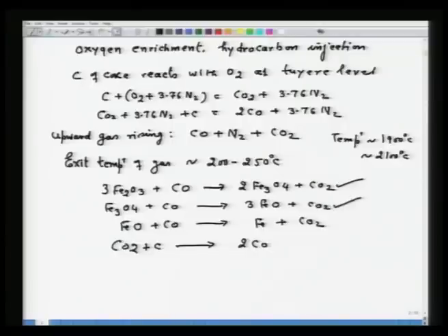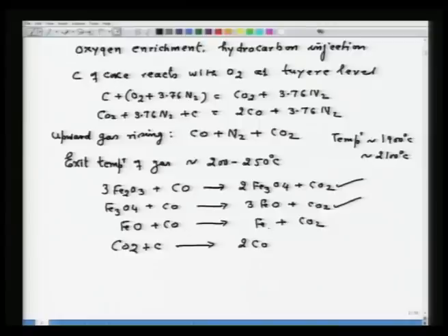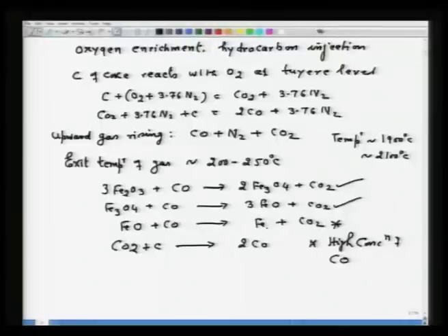Now, one important thing to note, these reactions do not require a very high percentage of carbon monoxide. So, they can occur towards the upper region of the stack, whereas the reaction FeO plus CO is equal to Fe plus CO2 requires high concentration of CO, and at around 900 degrees Celsius, the equilibrium concentration of CO in CO-CO2 mixture should be around 65 to 70% for FeO to be able to reduce to iron.